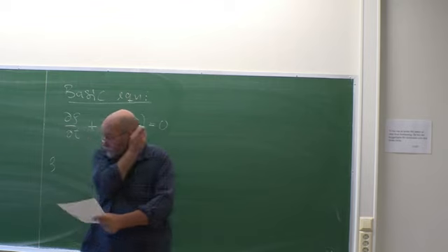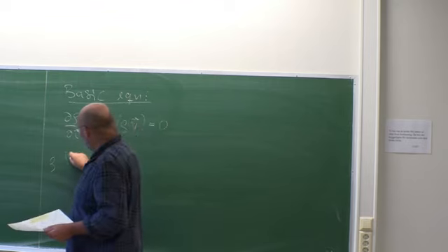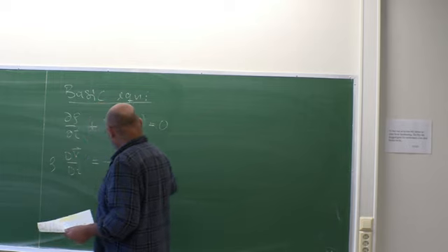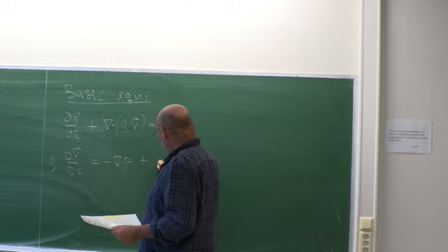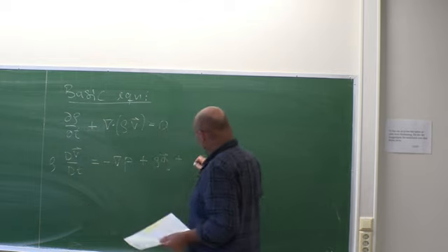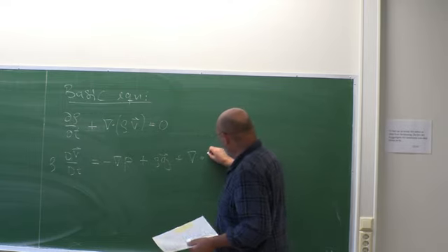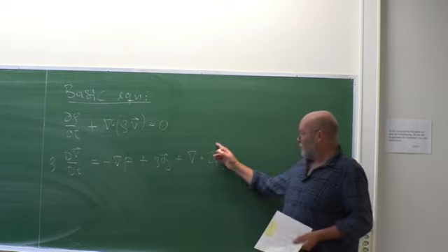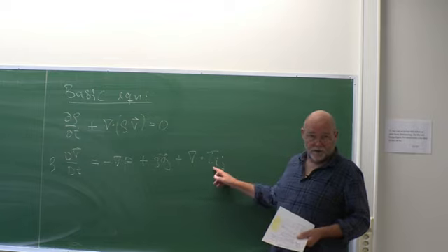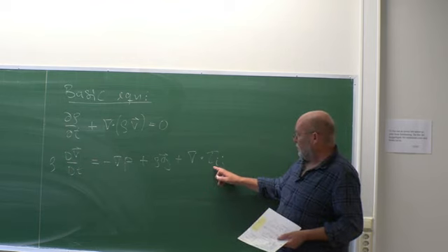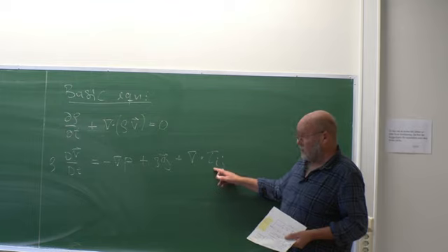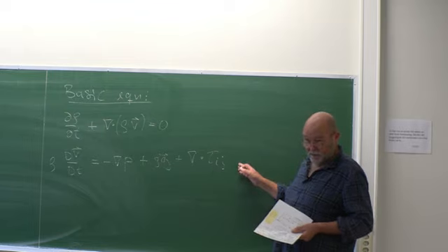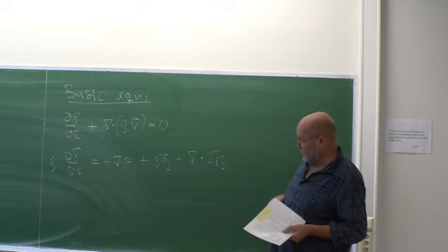Then we have the momentum equations. You can write them several ways, of course. This should be one way. You have the pressure gradient, we have the gravity, and then finally we have here the divergence. And here comes the total stress tensor, like that. Meaning, we haven't even said whether this is a Newtonian or a non-Newtonian fluid. Also, inside here, if it's a compressible flow, you will actually have a divergence of the velocity field, because in general, that's not going to be 0 anymore.